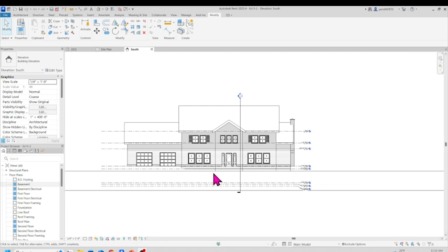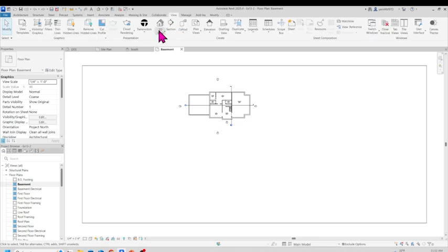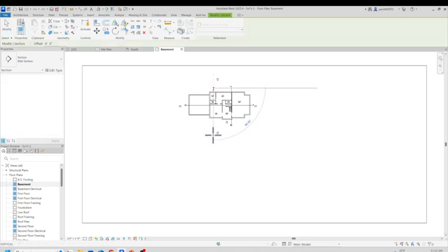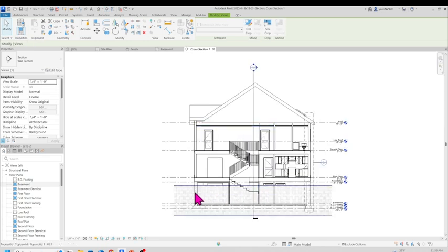Right now, the way we have it, this 10-foot layer is going through our basement, so we've got to excavate the basement. Let's go to the basement area and draw a section. If you don't know how to draw a section, you can go to View, and from View you can pick a section, and then you can draw a section like that. So if I click on one of these sections, you can see the basement is solid, it's not void, and we need to excavate this stuff.